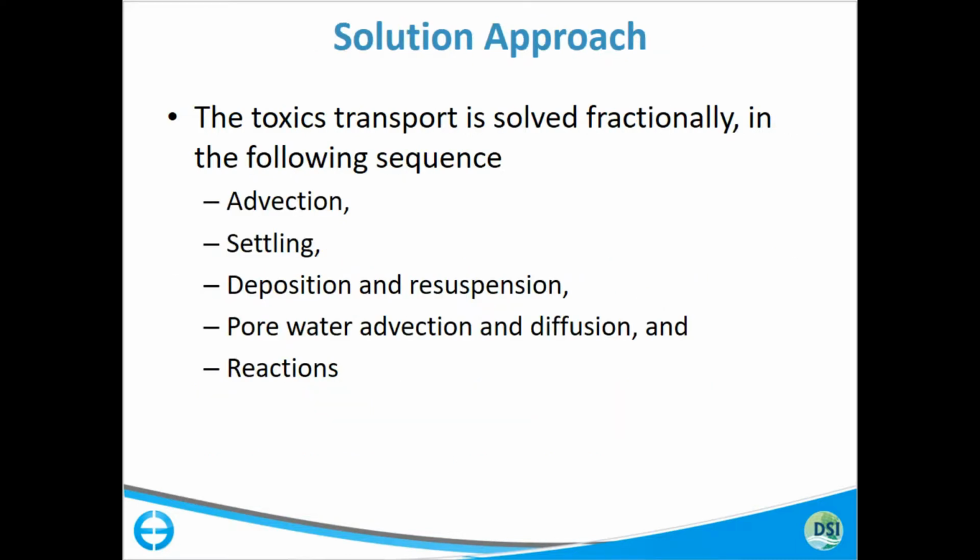Yep. So you've got this advective diffusive equation. The way EFDC solves that equation is the first thing it does is use the dissolved phase transport with your external sources and sinks. And it goes through the advection diffusion step. I think it's in the documentation as N plus 1/4. So you finish with your advection diffusion step.